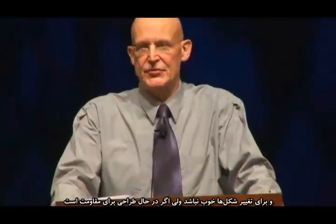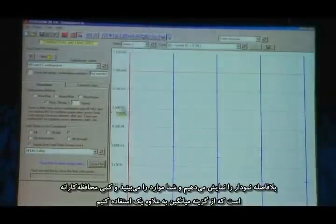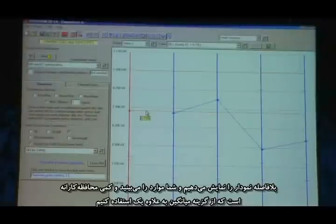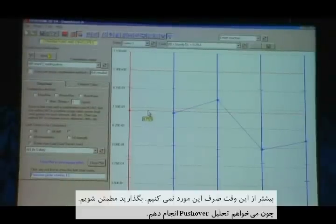Maybe not so much for deformations, but if you're designing something for strength, maybe using the mean value for the strength demand capacity ratio isn't really such a great idea. Maybe you should use mean plus 1 standard deviation. And if you think about it, it actually is maybe not a bad idea. You can also do that. There's an option here for mean plus n sigma, and n is here 1. If we plot this, and we do the same thing here, it's now rather more conservative because it's using the mean plus 1 sigma. Now, I'm not going to spend any more time on this.